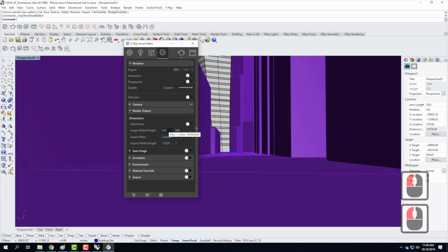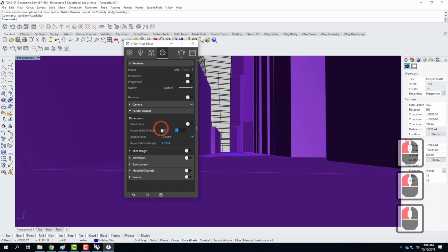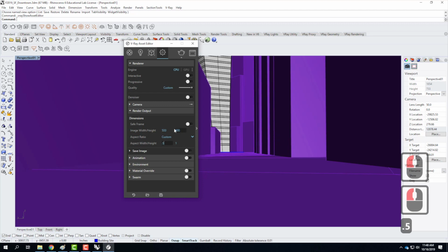So when I do that, I'm going to go to custom here, and I'm going to set my image width. Let's do it at 100. I'm going to do these as small numbers. And we'll see if it'll let me fix this one to like 400. No, it's forcing me into this. All right, so let me do it at like 0.3. That's 400 high, so I'm rendering tall and narrow instead of the other way around. I'm doing these as really small numbers, so my initial rendering is going to be small until I confirm that it looks the way I want it to look.